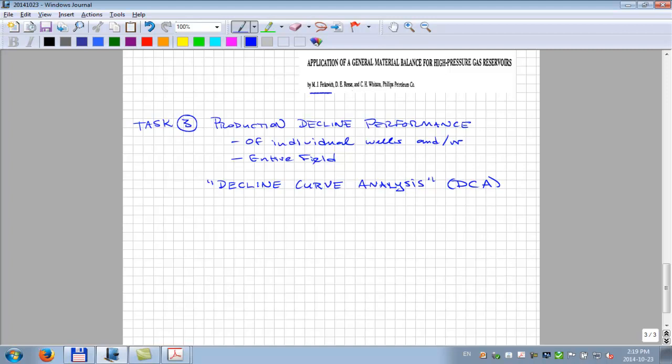They didn't have programs that you could best fit with an equation and so forth directly. So it was the decline. That's pretty clear. It's production decline. And in the old days we used this kind of graphical extrapolation of the decline that started, where you create a decline forecast and it's some curve, a straight line or a curved line, and the analysis is basically the study or performance of how decline curves look.